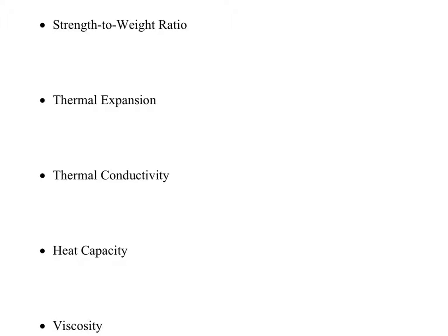Okay, so this is toward the end of materials now. In the boom lever competition, what you guys did is the exact thing in the first term. Strength to weight ratio. That was exactly what you measured. How much it could hold divided by the actual weight of the material. So materials have strength to weight ratios. You take the ultimate strength, you divide it by the actual weight of the material, you get the strength to weight ratio. Thermal expansion. What is thermal expansion?